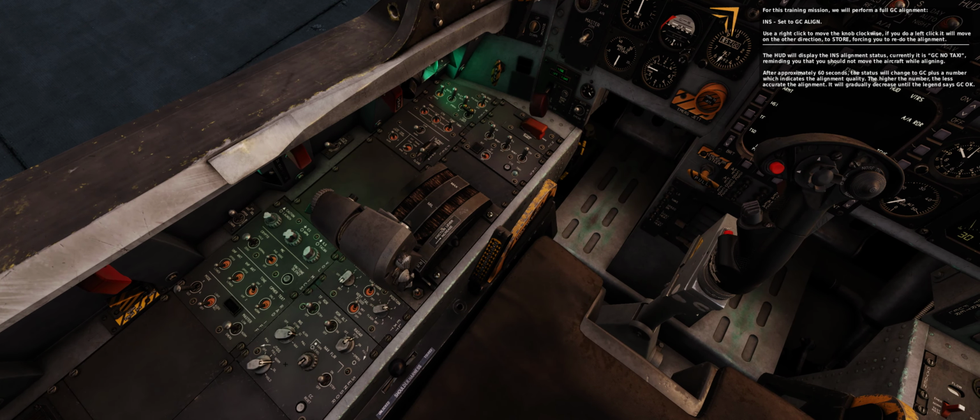You can see that the latitude and longitude shown by the UFCP on its second and third lines match, but not exactly. Let's input the correct latitude from the knee board, employing the UFCP keypad. First press SHF and 2 to enter N for north, the value is entered on the last line of the UFCP, called the scratch pad. Good. Continue by entering the numeric part of the latitude, 3, 7, 4, 7, 1, 0, 6. A leading 0 must be included if the latitude degrees are less than 2 digits. Do not input the decimal point, as it is assumed.